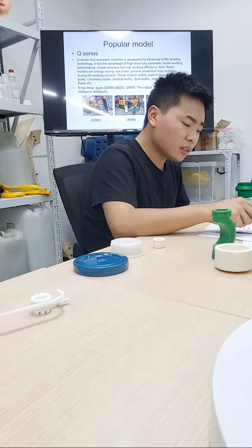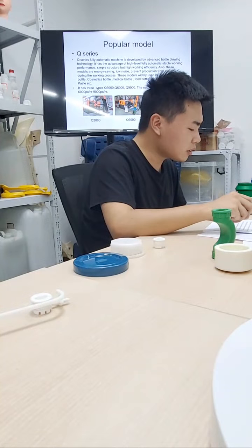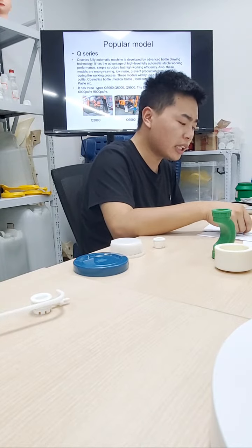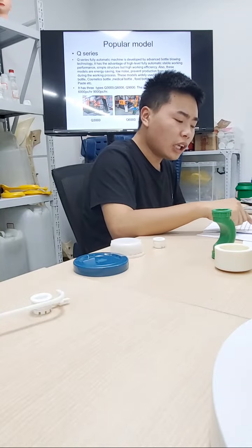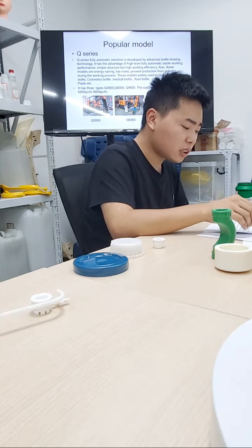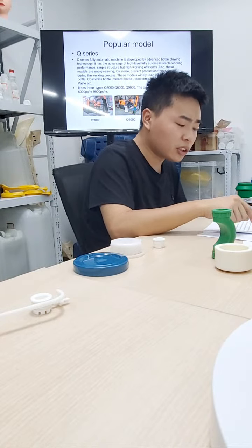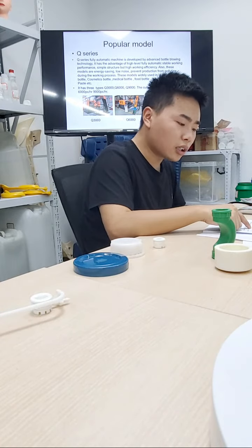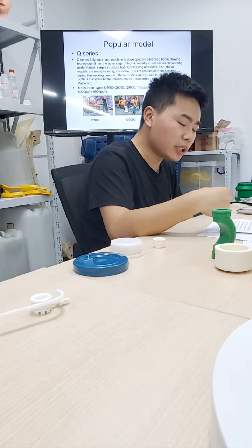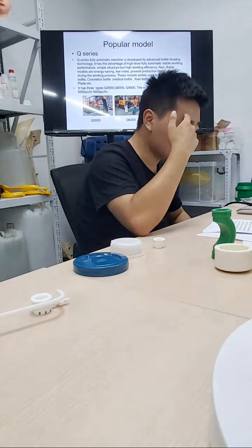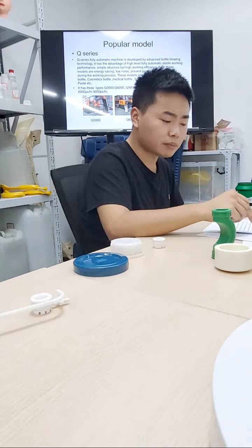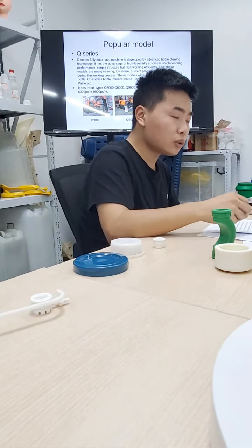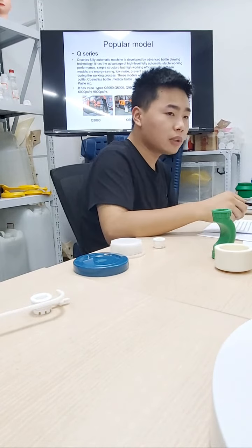This machine has 3 servo motors. One is for the rotary chain, one is for the mold clamping, one is for the stretch rod. If the machine has over 4 cavities, servo motors will be added, like the Q6000. The Q3000 has only 3 servo motors because it is only a 2 cavity machine, so there is no need for too much on the preform chain.